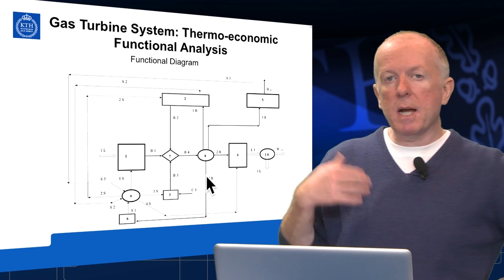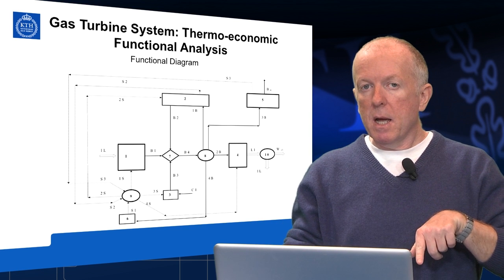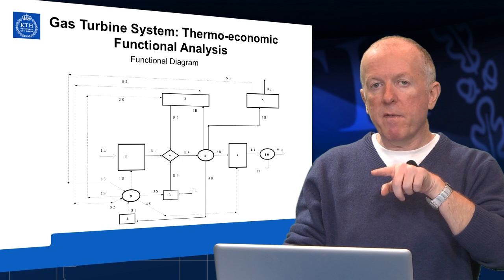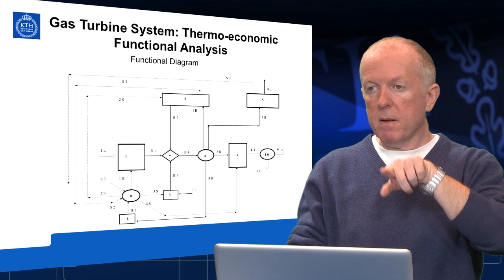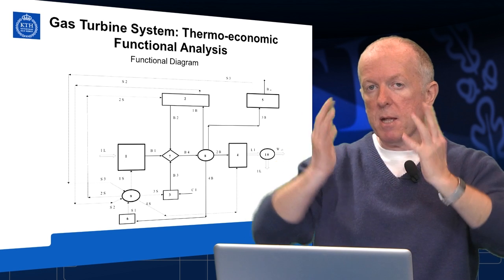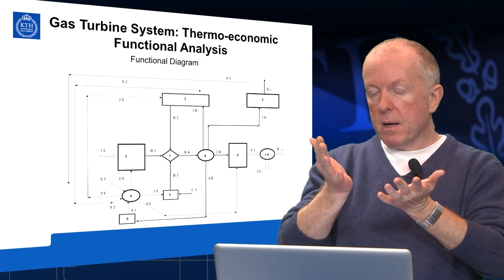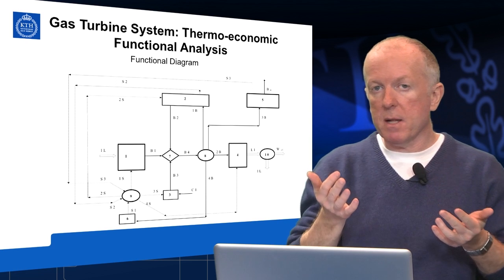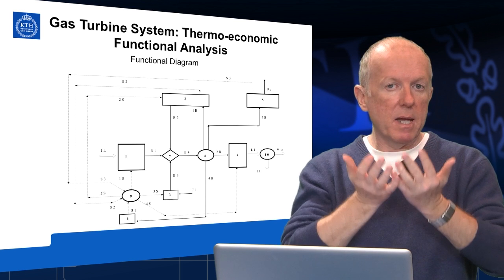At the end, the very last part of the exergy distributed by the branching unit 8 is given to the last virtual component. So still the flow 7 contains exergy. This flow 7 is given where? It is given to the external environment, mixed from the chimney to the external environment. So you have a closure of the entropy cycle between the flow 7 and the flow 0, which represents the fresh air into the environment, which has to be closed by the role of the environment.